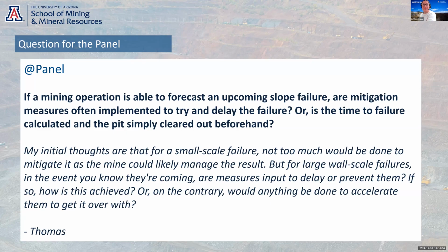I think with most geotech questions, the answer is it depends. It really depends on the size of the failure, the rate it's moving, the location within the mine, and the risk that it poses to the operation. So I think key for me would be understanding the failure that you have coming at you, where it would be, and what the impact would be.